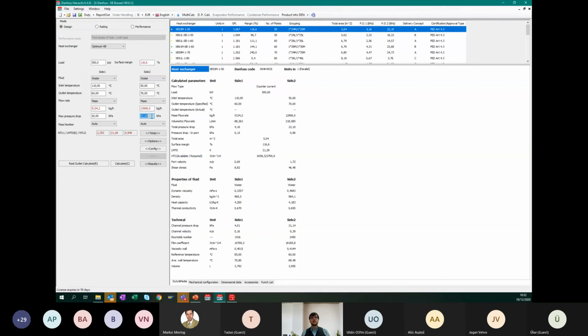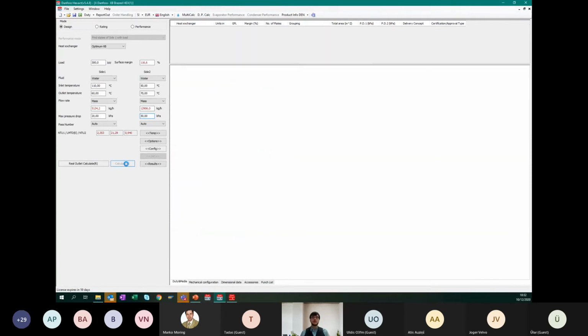That's why, when you design systems and you see that you are limited when you select your heat exchanger, limited by the secondary side pressure drop, maybe it's not the critical side and you can actually add a few extra kilopascal there. Maybe I can go even bolder. Let's make 30 kilopascal on the secondary side.